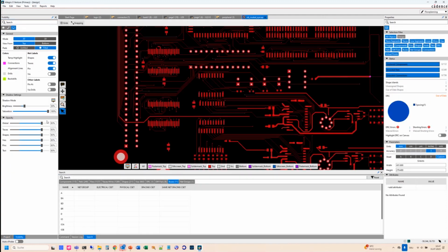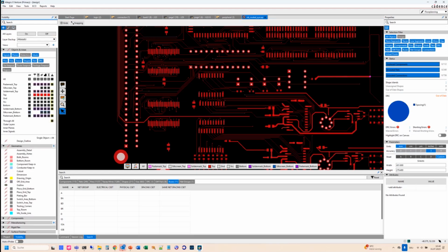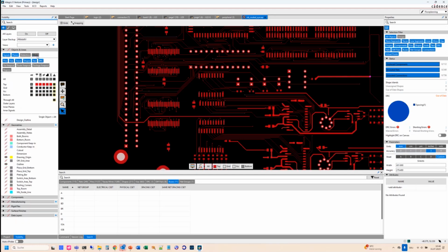It takes a second, and then you see, this looks now like Presto. Visibility pane of Presto. You can also go into the 3D canvas. You can highlight nets. You can influence what layers you want to see, all these kinds of things. Same look and feel as Presto. We are now in the floor planning mode, the button here in the upper right side. We can also go into viewer, but then we can just view things. So it's also good for a review, but you cannot really edit the board then.